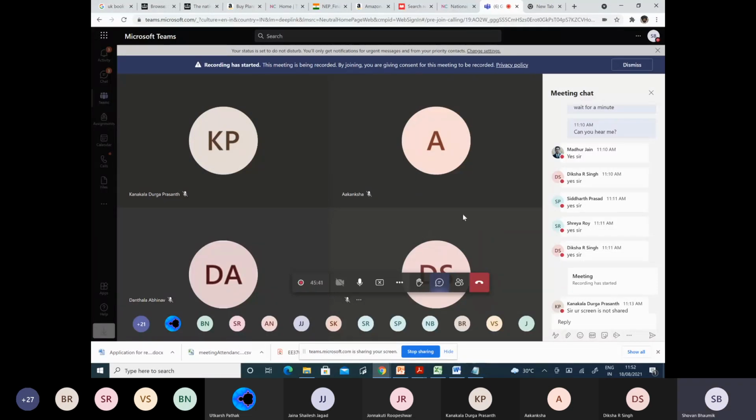So this is the way we can think about it. If you see, there are two aspects. One is time domain, one is frequency domain. Whenever you are taking an instrument, you have to analyze both. If you don't analyze the frequency domain, that means what will be its bandwidth, what will be the cutoff frequency, what will be the corner frequency, and you use that instrument for all sorts of inputs, then you may not get the measurement output for very high frequency components. So you have to be very careful while choosing the instrument.